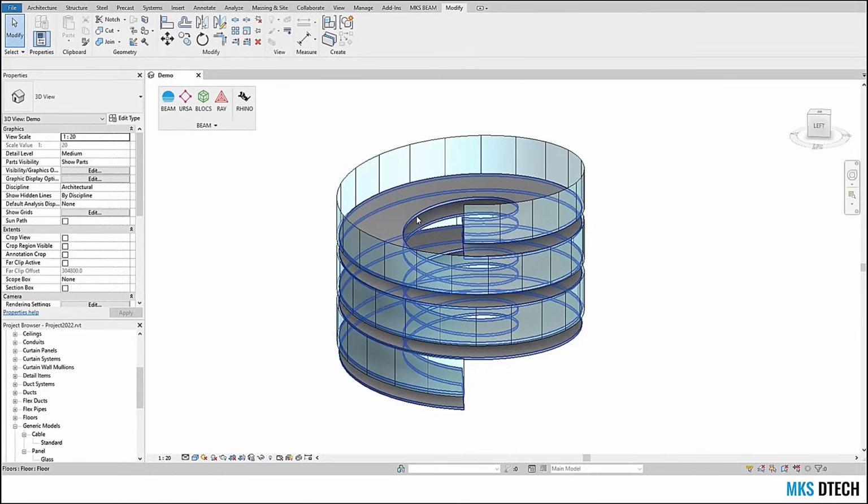Obviously, it would be really good if we could cut these kind of floors with the shafts already. At the moment, it's not possible, but another workaround that came into my mind is having a void family, maybe, or generic model and then cut geometry. But anyway, good question. It's good to experiment a little bit more also with these kind of shapes.